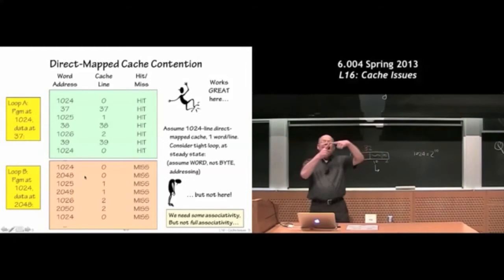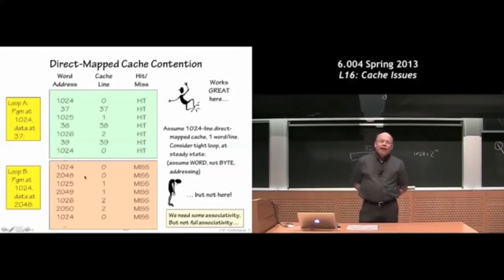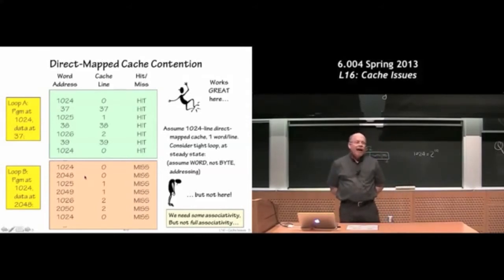The addresses are colliding, in other words, they're mapping to the same cache line, and we're not finding anything in the cache. Now, if you want to amuse yourself, you can Google around and find programs that have been designed to break the Intel caches, in other words, designed to produce nothing but collisions. Your fantastic 2 gigahertz machine that you're so proud of actually turns into a couple hundred kilohertz machine because the caches are no longer working.